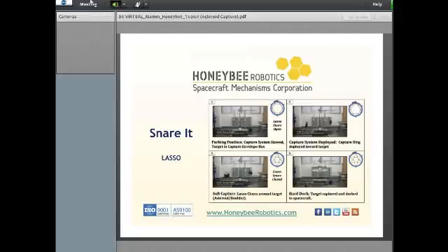And the concept surrounding our docking system, or in this case, applying it to an asteroid capture, would be to influence the target minimally prior to soft dock. And so effectively how this system works is that you deploy the ring, you deploy the snare around your target without touching it. So there's zero impact prior to being in position, ready to snare or capture it. So that's the position that's represented by block 2 in the upper right corner here.